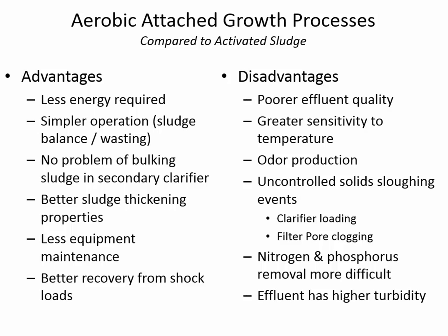Also, if you're blowing air, or if air is just naturally percolating through a filter media that has wastewater sprayed all over it, obviously you're going to get some smells from that. And so where people are living in close proximity to trickling filters, you have to account for the fact that odor production can be pretty significant, especially sulfur-containing wastewaters, which tend to have a lot of odor production.